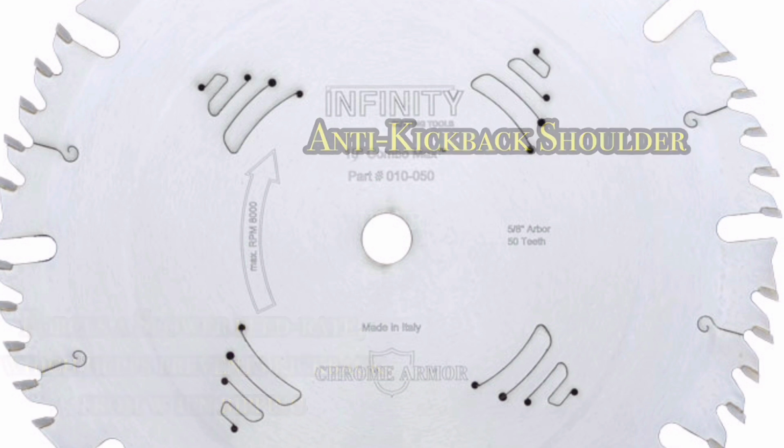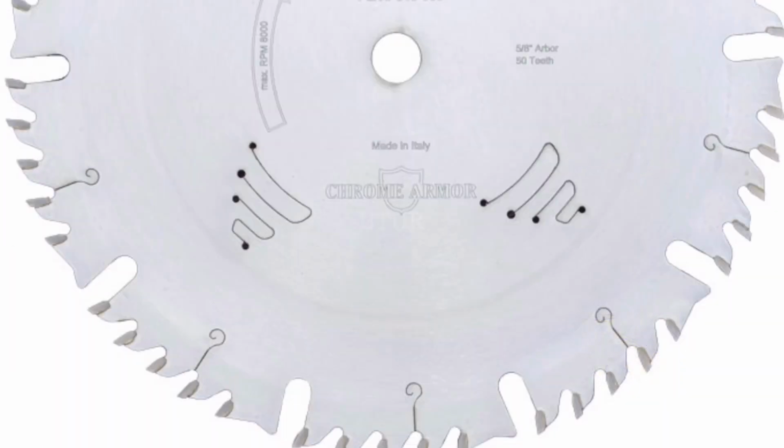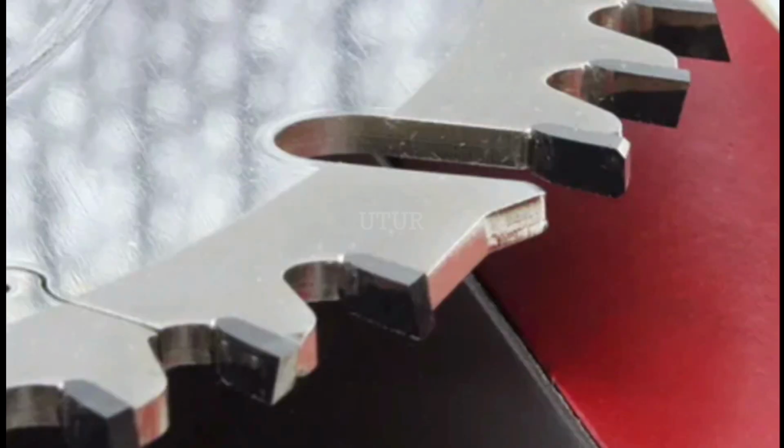If you find it laborious to change a blade, it gives you the added advantage of leaving one blade in your work tool. This is a quality tool as it's got laser cut expansion holes, which reduce noise and vibration, big ripping gullets, fine cross-cut teeth, and extra large carbide teeth that allow multiple resharpening.